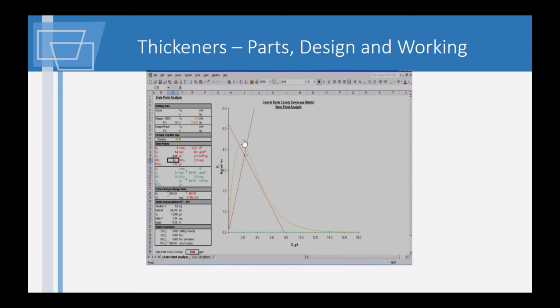However, this is not a realistic approach to dealing with unexpected high flow events that occur from time to time. Typically, the only other option available in this scenario is dosing your RAS line with some chlorine. A quick dose of chlorine in the RAS can attack the filamentous bacteria and lower the SVI. If the chlorine dose was able to drop the SVI down to 200, we'd find ourselves back in the safe zone. However, this option is only available to treatment facilities with the proper equipment installed.